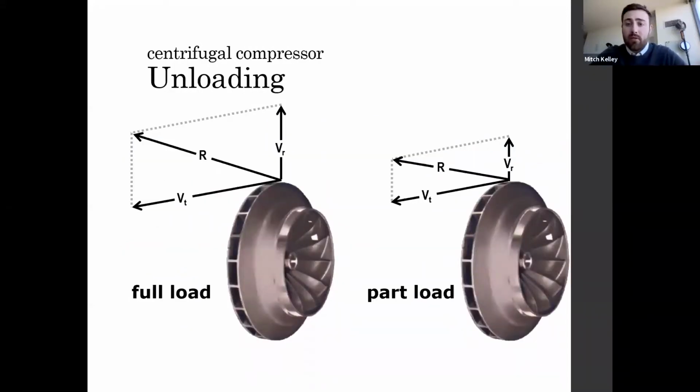Now, when using a centrifugal chiller in a heat recovery application, it's extremely important to understand the compressor's part load operation. The larger pressure differentials required for heat recovery design also tend to reduce the unloading capability of the compressor itself. Consider a given diameter compressor impeller that rotates at a constant speed.